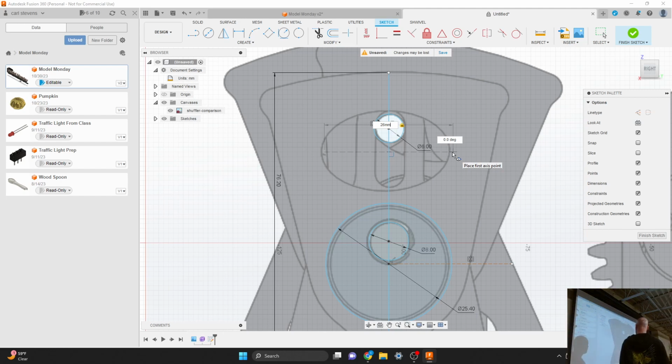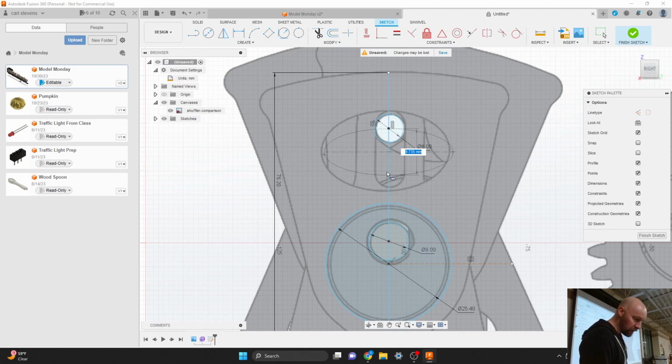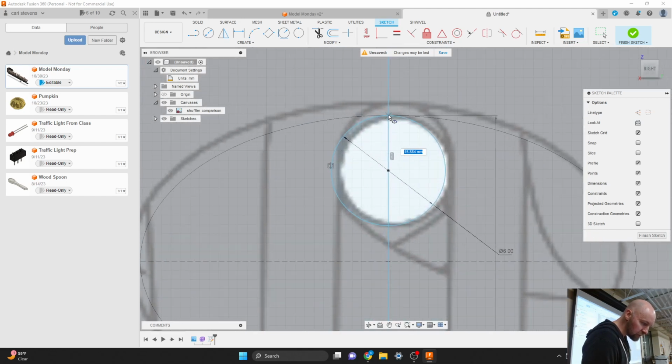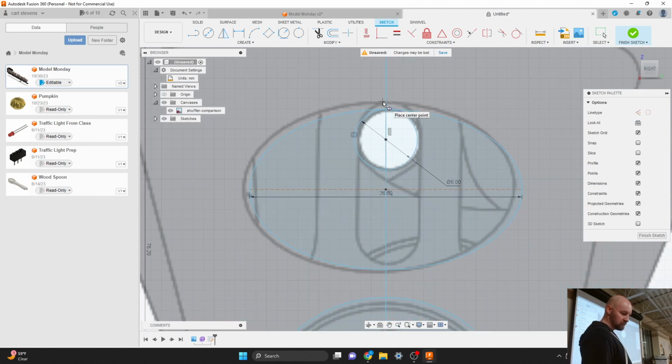Unlike some of the other tools, you hit the enter key to place this dimension. We have to click. So we type in a dimension, and then we click, and then we move our mouse out another way, and here I'm just going to click on this endpoint of this pin that I've got up here, so I make sure that I'm tangent to that circle.